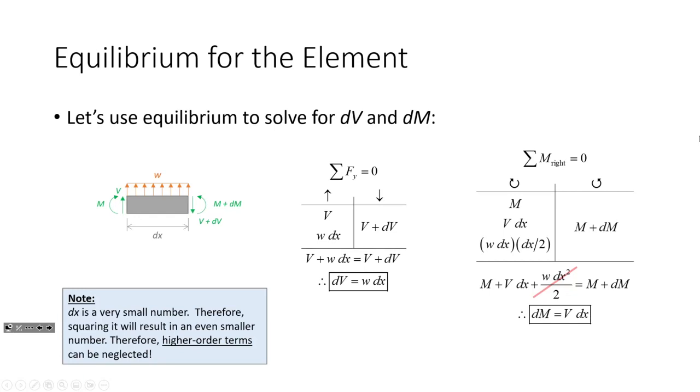But then look what I did here. Look at this. So I've got the load, which is w dx, times the moment arm. What is the moment arm? Well, I idealize that as a single point load halfway over. So that's how I get this. Does that make sense? So the load is w dx and the moment arm is half of dx. Does that make sense?